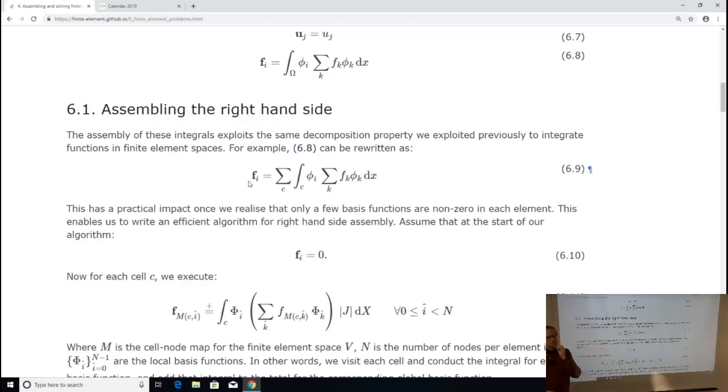Yeah? Why did you say 6 triangles? Because on average, so you can have an arbitrary number of triangles meeting at a point, but if your mesh generator is being well behaved, it will try to make triangles that are approximately equilateral, because all of the errors will come out better that way. And 6 equilateral triangles meet at a point. So if you have a reasonably high quality mesh, there will be about 6 triangles meeting at each point.